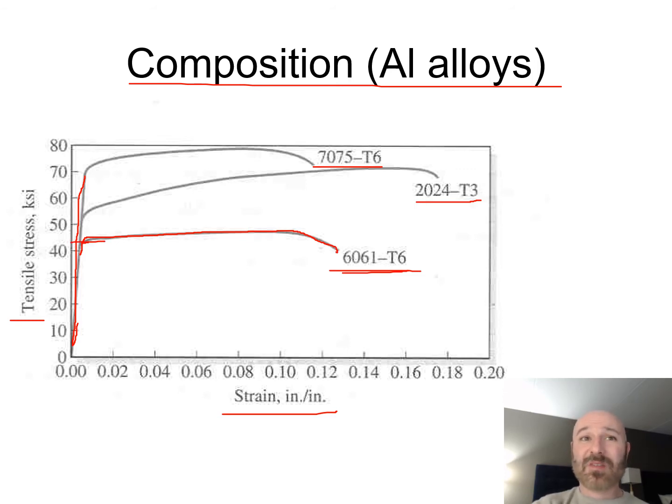So if we look at this, is that the tensile strength that's acceptable for us? Or do we want to go a little bit higher up here? We want something over 2024, but we might get a little bit more strain out of it. All decisions you have to make in this material selection process. The one thing to notice is just that modulus of elasticity is not always going to be enough information for you. You're going to need some of these other material properties to help you make those decisions.